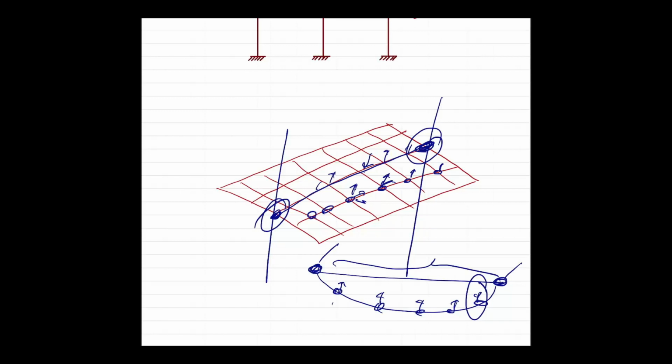So if you want to stitch the beam to the slab, you might need to discretize your beam along its length, and then put a condition that links these two. You may not need to link the rotation of the beam to the slab. It might not be necessary because the slab rigidity might not be that significant in bending compared to the beam. The beam is very stiff flexurally in comparison with the slab. But the deformation should go together. So you stitch the deformation, but you may not stitch the rotation. If you can stitch the rotation, well, fine. And then you run the second round of analysis, you might find that your beam and your slab go together, and that makes perfect sense.